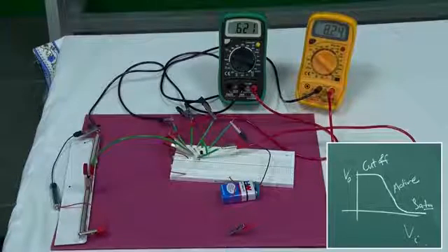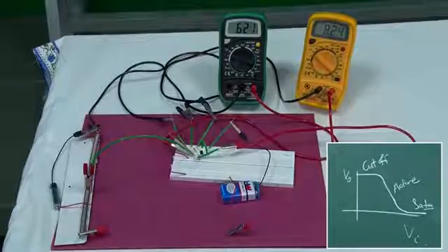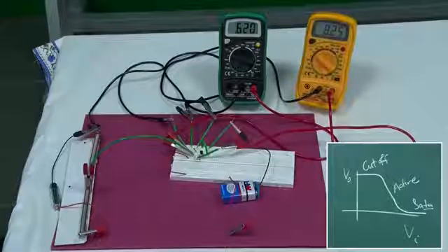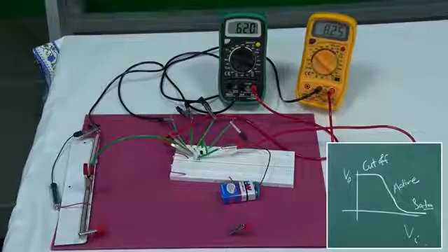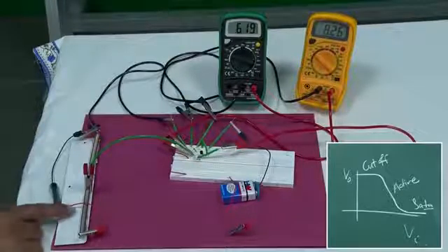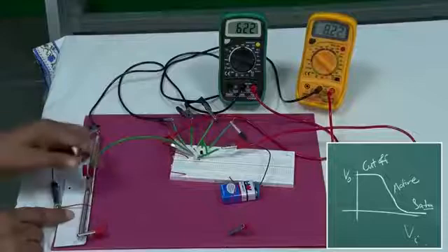So, what reaches base will be very small, it will be a fraction of voltage, 0.2, 0.3, 0.15 type volts on the base. But the input voltage that I am supplying from my battery, from this potential divider that I had made, is 0.620 at this time, and the collector voltage is 8.26. So, it is going down. So, now we are reaching that active region.